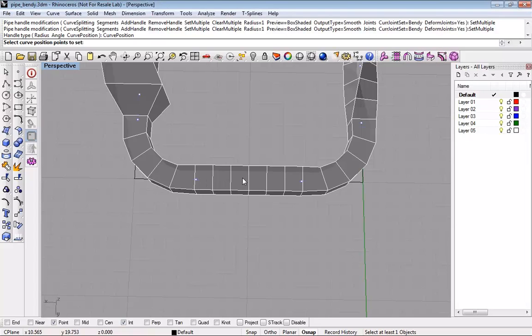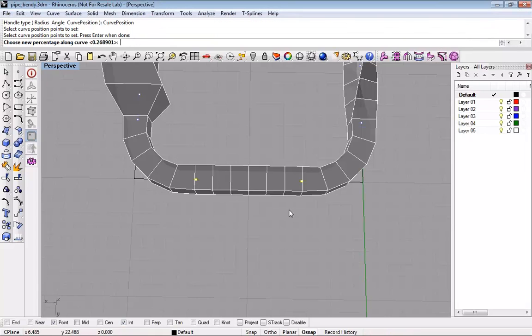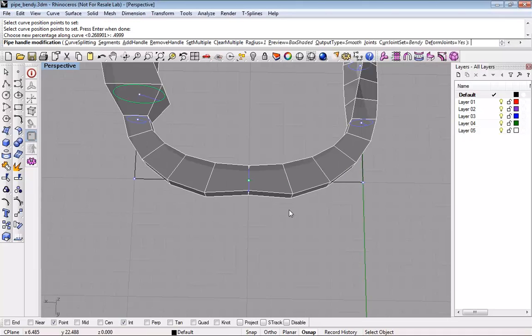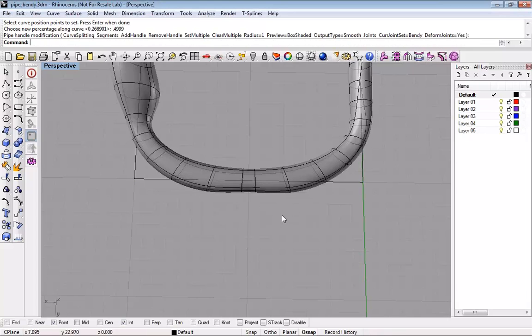he'd be 0.25. If you set them both to 0.5, then the pipe is exactly 0 width, and I think when we do some of the math, things get degenerate. We can't take cross products properly. So for that guy, you should be able to select these two and say 0.4999 will work. Just exactly 0.5 is too close, and if you set it over 0.5, then it's flipping inside out, which may not give you the result that you're looking for either.